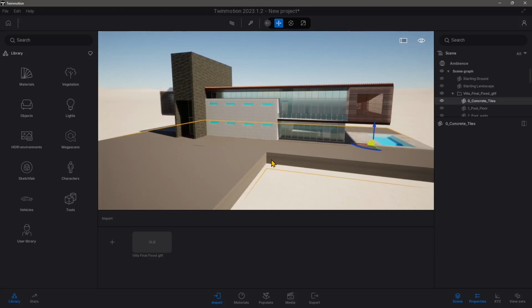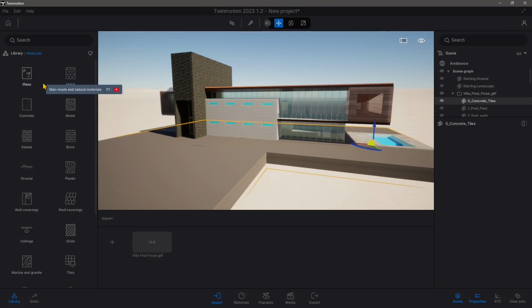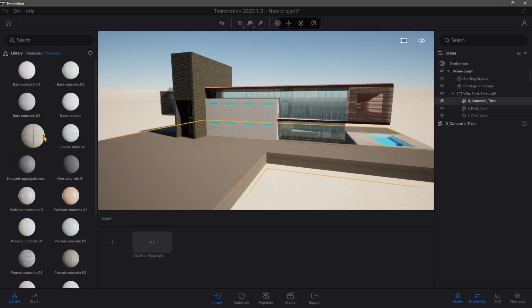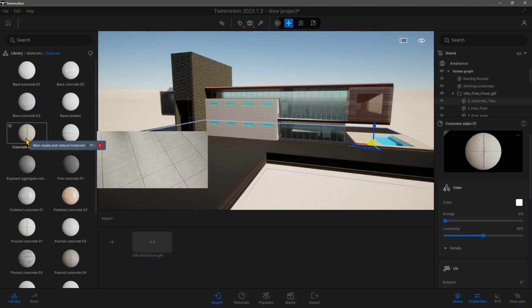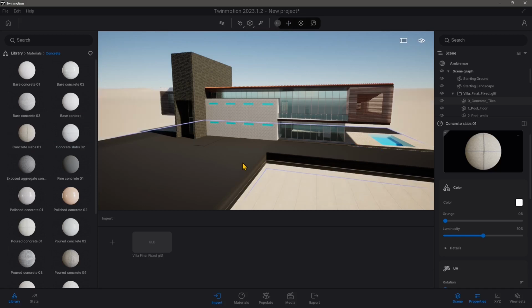Here, what I'm going to do is just show you the mapping issue. You can see the base. Everything else looks pretty fine. We can definitely adjust the size of the texture, we can change the texture, but if you click and drag here, something is not good. There is something wrong with the mapping. So geometry is important, it needs to be mesh. Materials are important, and you can see now that they are visible, but mapping is important too. You can click there and change it from box mapping to cube mapping, and now it should work. Just click and drag, wait a few seconds, and there you go.